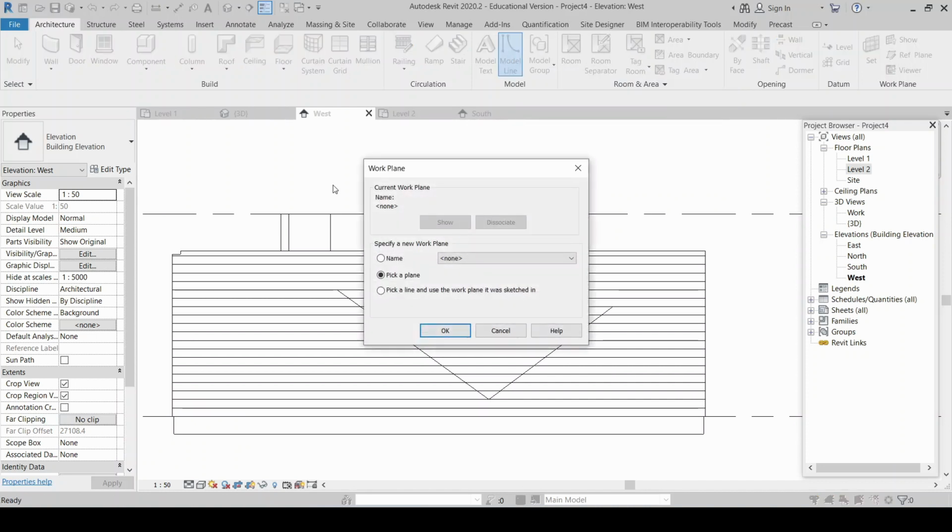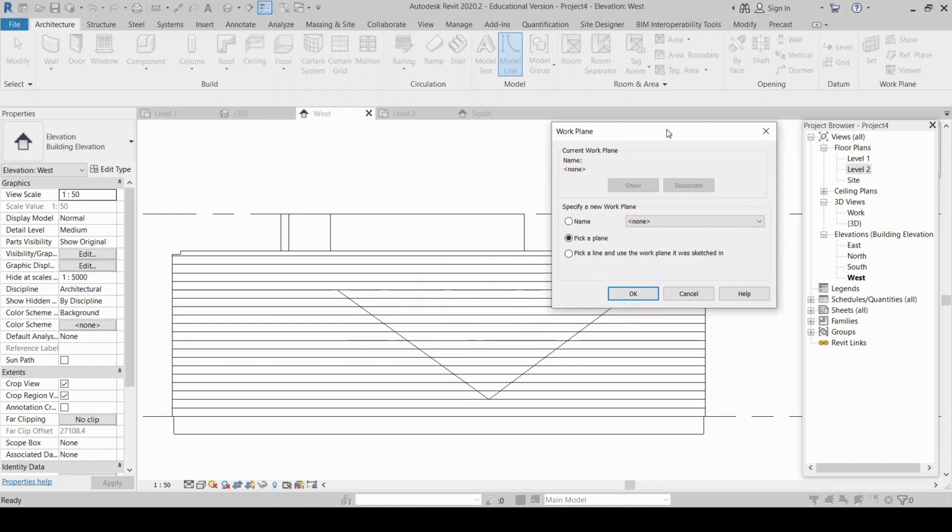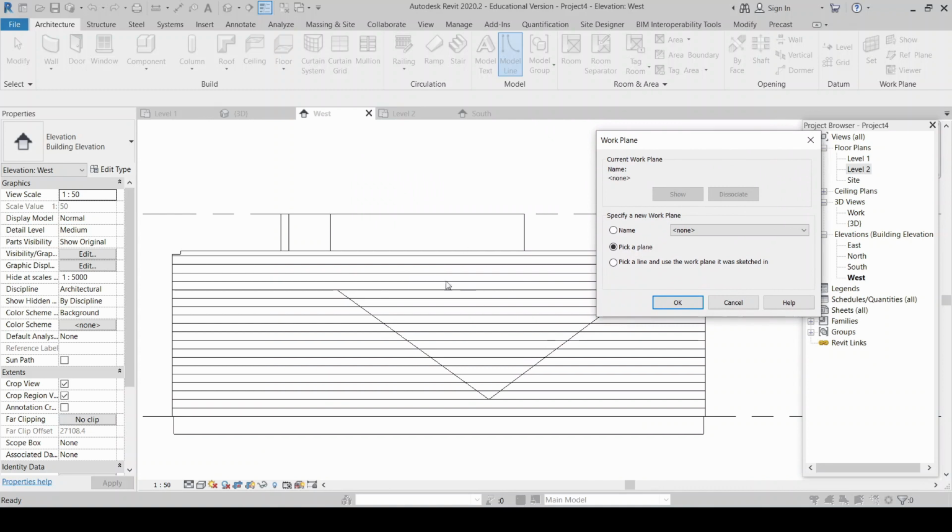If I click on that, I get a little pop-up box. So the problem we have with lines in space is Revit wants to know where they are. At the moment, if I drew a detail line in this view, it appears effectively at the very front, on the cut plane itself. Revit doesn't need to know how far forward or back that line is, it just appears. When I draw a 3D line that's actually physically in space, Revit needs to know where it is forward to back in this view, because it could be in front of the wall that I'm looking at, or it could be way back, 30 meters beyond the back of this wall here.